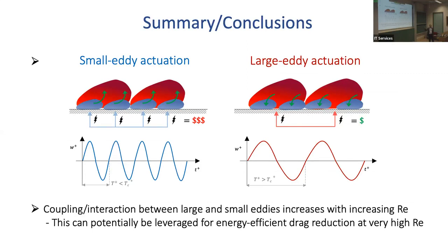These large structures are going to be important at 1,000, and at 2,000 they're still not active enough. But once you get to 10,000 or 100,000, they're the main show in town. That near wall cycle is always going to be important, and 100 is always going to be good, but it's just the expense. But this is a really good question.